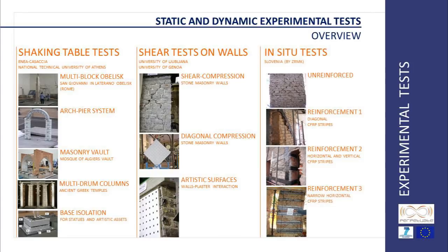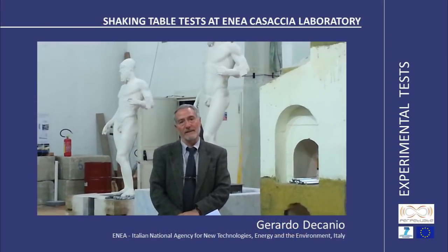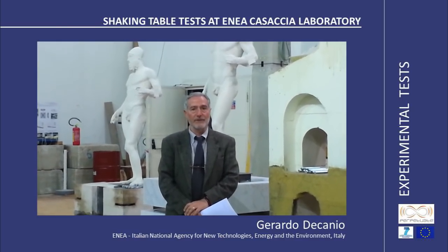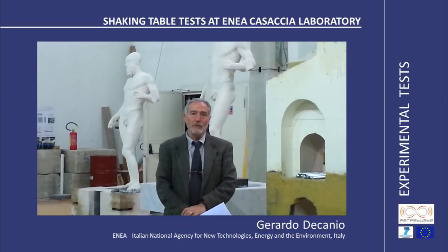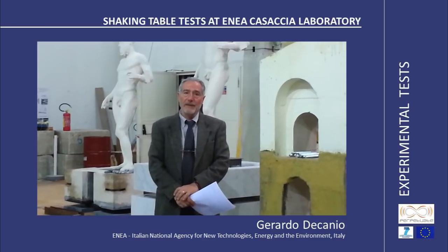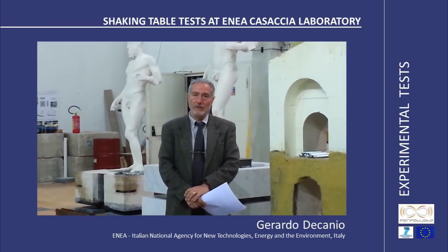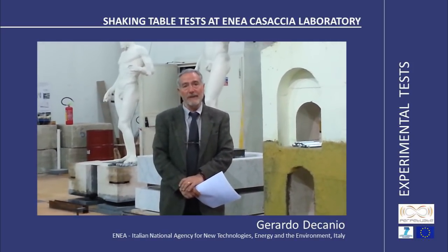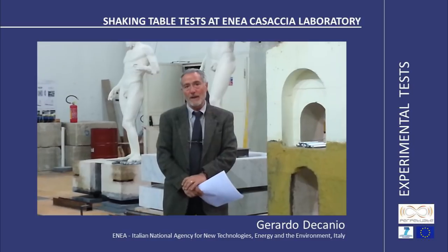The third set of tests, carried out in situ, were oriented to assess the effectiveness of some strengthening techniques on masonry walls. The aim of the shaking table tests in PERPETUATE was to define the proper limit state for cultural heritage assets and to correlate those limit states to the seismic input. It was obtained by the direct measurement of the displacement at several points of the structures and to correlate those displacements to the damage states.